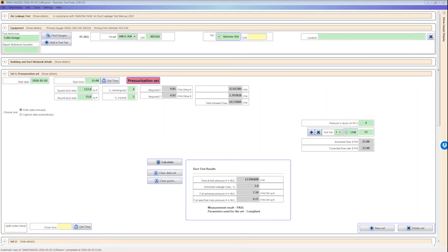It is difficult to get in there and seal existing ducts, but with the system that they have, they can actually do that. Interestingly enough, what they use to pressurize their system is exactly the system that I described to David, which is a 6,000 fan in series with a 4,000 fan. That's what they use to pressurize the ducts and actually measure the leakage of these massively leaky systems. So there is an opportunity there.